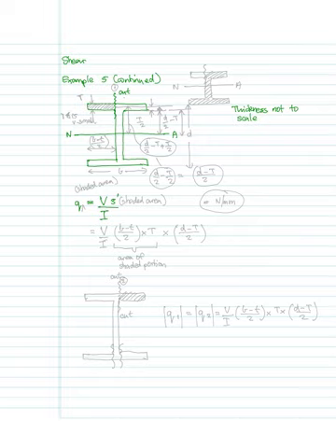And remember that the units of the shear flow would be newtons per millimeter. We've already made the assumption that the thickness, capital T, is very small, because we're assuming that it's a thin walled section, and so the transverse shear stresses disappear.